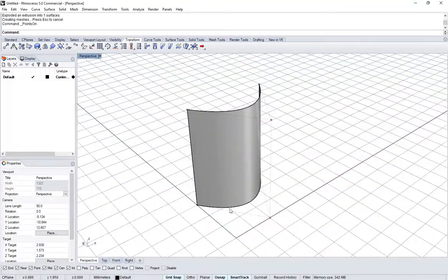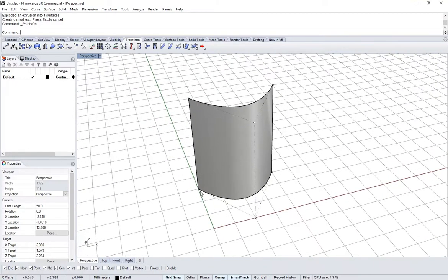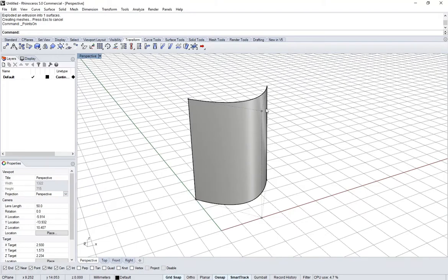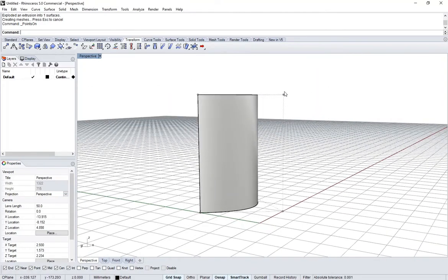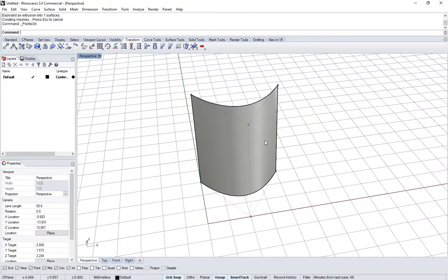And the control points are the same as what we had for the curve, but now we have control points for the base curve and the top curve, and then the two control points here that define that straight line. So control points for surfaces work exactly like they do for curves, except now we're dealing with curvature and control points in two directions instead of just one.